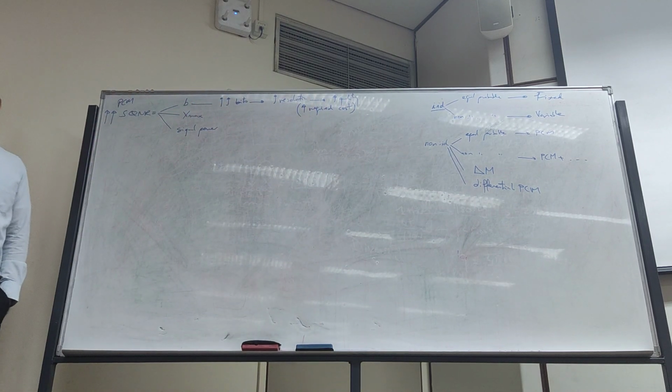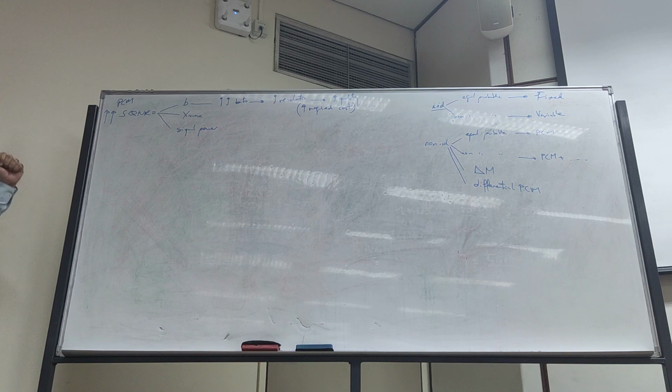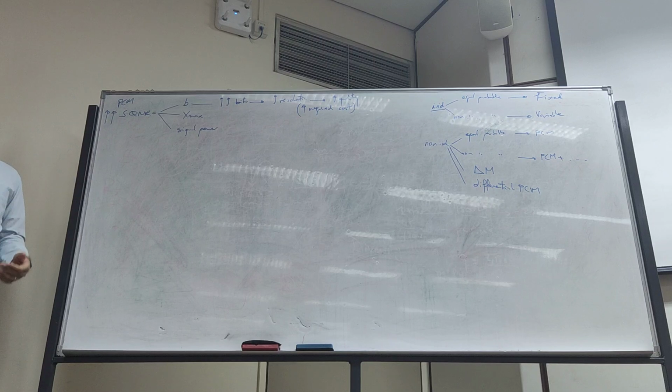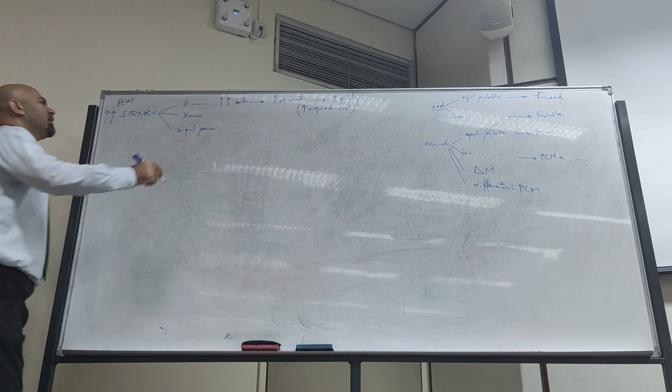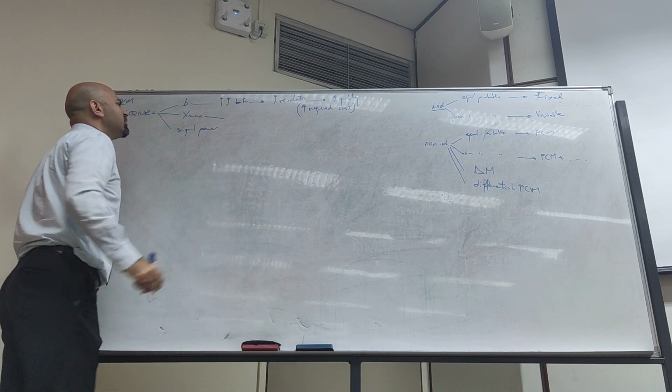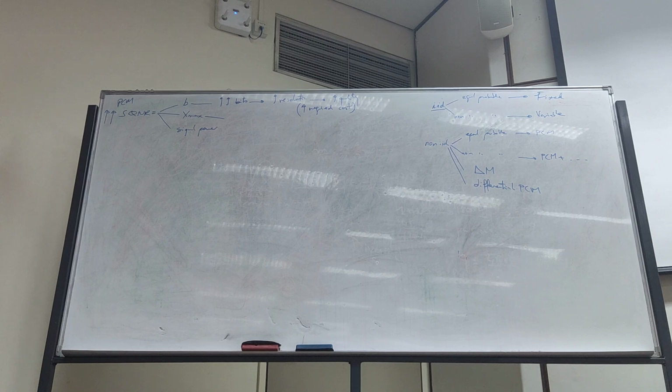Good. But you as an engineer are the one who should be aware of all the parameters. It's like a game. You have to increase this, you have to increase that, you have to check what your application allows: whether you can increase the cost or you have a strict restriction on the cost, so that you know what to change. Good? With the X max, here X max was in the denominator, right? So whenever we increase X max, our SQNR will decrease.